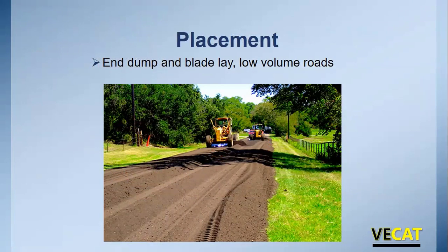Occasionally we'll see this in areas where they want to put down a very economical mix on a rural low volume road. And when you do this, it is possible. It can be done this way where they just do end dump and blade lay it. Seen it done on low volume roads and on places where they were making a pad for temporary parking and that kind of operations. The things you have to be aware of and be cognizant of with this process is you're going to be moving that material around with the blade, so you've got to be careful not to segregate it. And it's probably not going to go down as smooth as if it was placed with the screed.